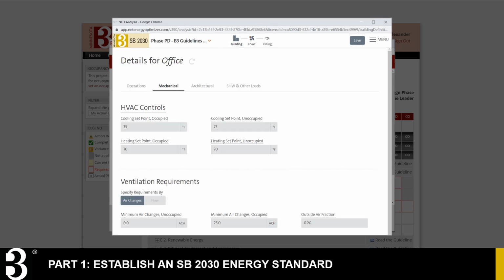Space asset areas can be modified from their default assumptions to better reflect actual conditions, such as geometry, schedule, set points, and process loads. These are important to edit early in the design process if the change is likely to significantly impact the building's energy consumption, such as if the area of a building is anticipated to have much higher or lower airflow rates than a typical area of that type.